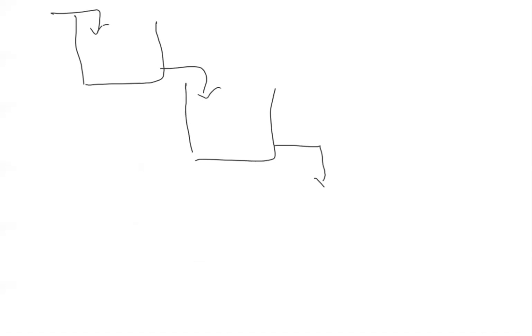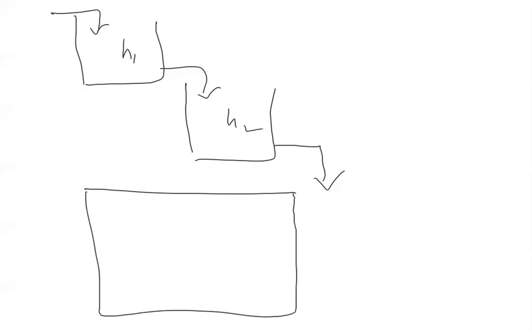Now, let's say if you take non-interacting, it is one directional, interacting is bidirectional. If we compare the responses within non-interacting, the effect of the first system is faster, the second system is slower, because the second system will become a second order system. So this is H with respect to time. When I'm writing with respect to H2, it becomes a second order system. For H1, it is only a first order system.